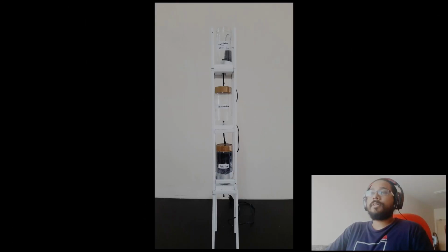The design for the water treatment device will have a three-staged water treatment system. Stage 1 will be coagulation and flocculation, and it will have a water pump installed to help with the flocculation process. Stage 2 will be sedimentation, and it will have a low flow to the next jar to allow for flocks to settle. Stage 3 will be for filtration.